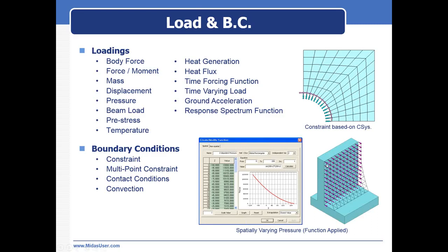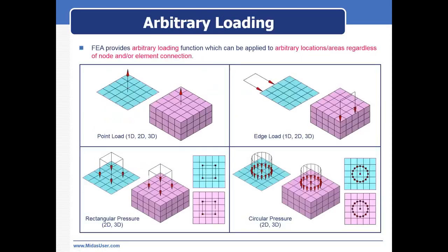Likewise, if we have some loading varying along the vertical height, then we can actually define the profile in curve and apply the loadings. So any sort of loads and boundary condition definition is possible. Another advantage with FEA is that we have arbitrary loading. That is, we can define the loadings without any nodal connectivity requirements.